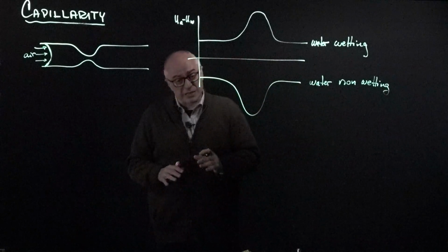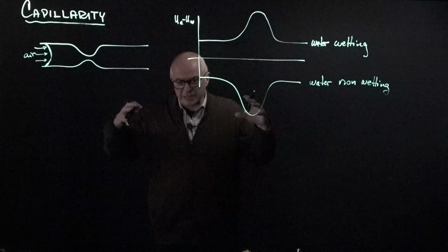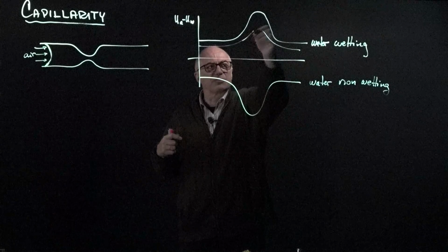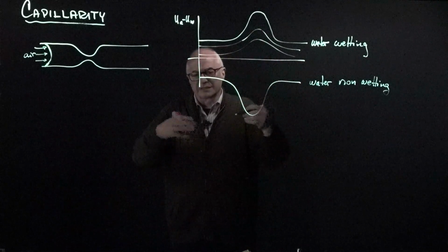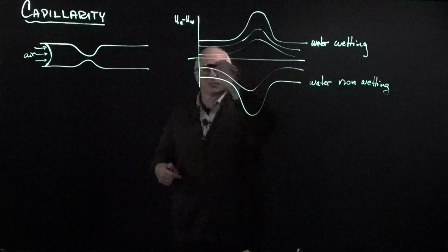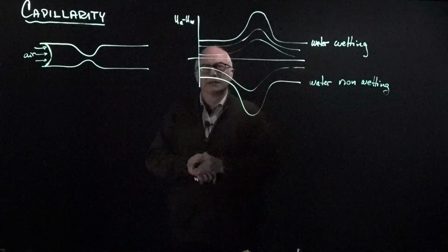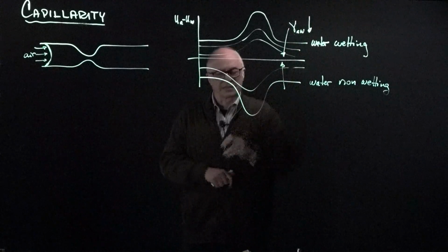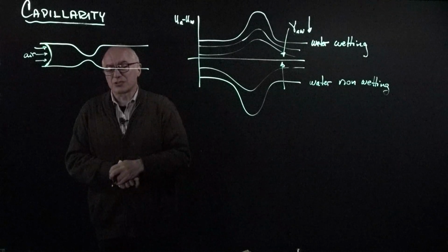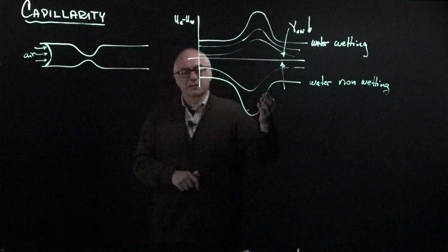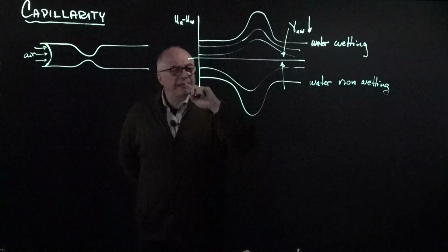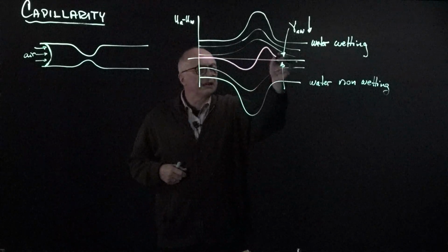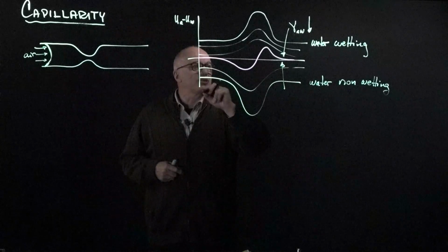Now, if I change the interfacial tension by, for example, running this experiment in a pressure vessel where I confine CO2 or the gas, this is going to begin decreasing. It's going to have the same shape, but it's going to begin decreasing because there is a decreased mismatch in the interfacial tension between the two fluids. So this is the effect of decreasing interfacial tension in both cases. I can run another test in which I play not with the surface tension but the contact angle, and there is one more case that would emerge, and that is that it could be coming here and then it jumps and it comes back. And now that is when I change the contact angle.